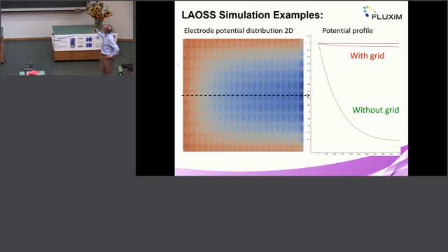Without any grid, we would apply a potential of 6 volt on the left, and then the potential would drop significantly to only 3.2 volts in the center or over here on this right-hand side. As we apply the grid, we see that the potential is much more uniform. The pictures, of course, with false colors are misleading. These wiggles here are really a very constant value across here, and that's much better than the case we had before without any metal grid.